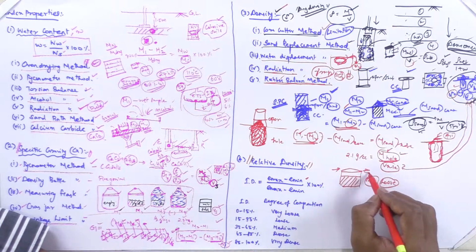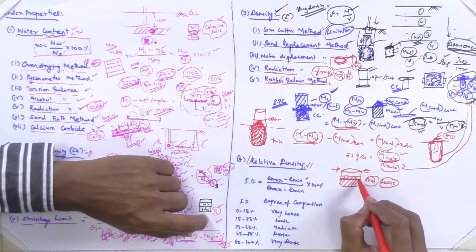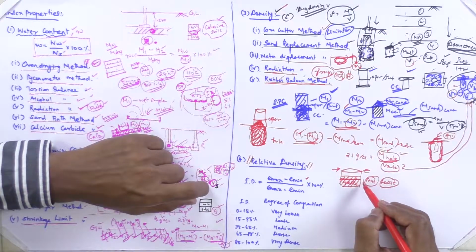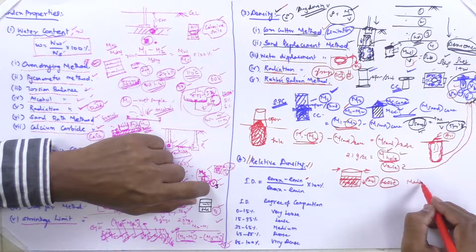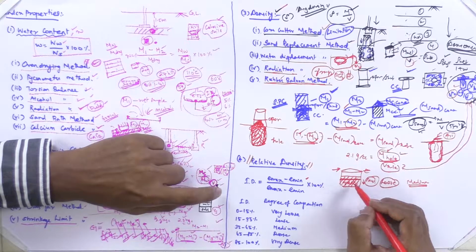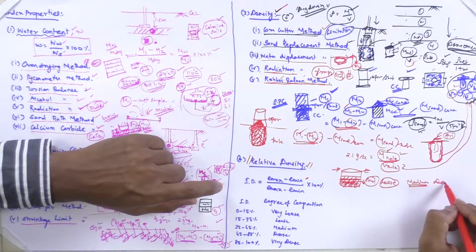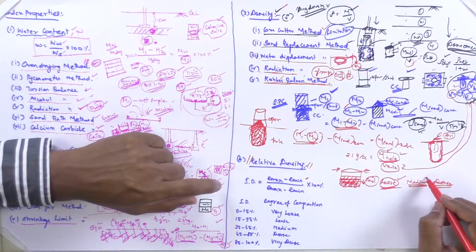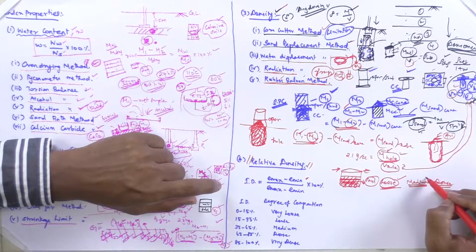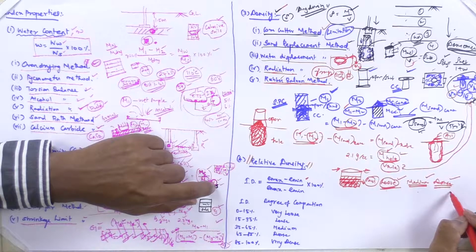If you give some vibrations, what happens? The volume decreases, which means the particles got rearranged and settled somehow. Now it may be in a medium state, then you are giving more vibration, it is further going down, now it has become very dense. So initially it is very loose, after giving some particle disturbance it is going to medium, then dense. So these are the different states.